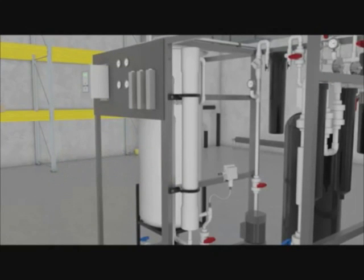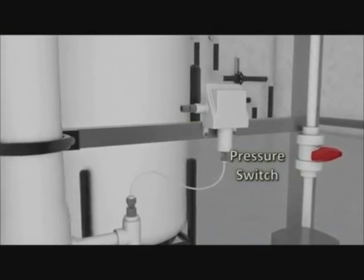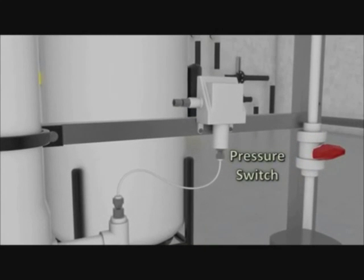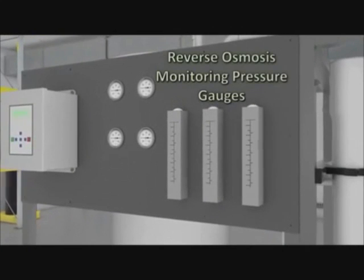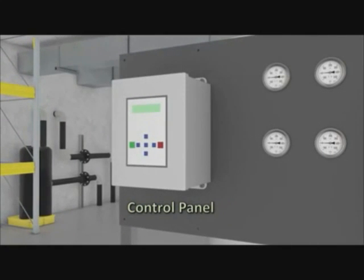As the water passes through the RO membrane, there is a low pressure switch to protect the pump against low inlet flow or pressure. There are panel-mounted pressure gauges to monitor the pre-treatment and reverse osmosis inlet and outlet pressures. The neighboring control panel is used to monitor water quality and facilitate operational functions.